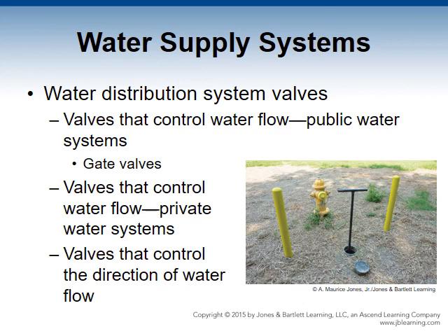Finally, you have the reduced pressure zone principle backflow prevention device. In addition to the two spring-loaded check valves, this device has a diaphragm-based spring-loaded relief valve located between the check valves. This device offers the highest level of protection because the relief valve opens and drains to the atmosphere, even if both the check valves fail to operate. It does require periodic inspection, testing, and service to ensure proper operation. These valves are essential to keeping our water system safe and free of contamination.